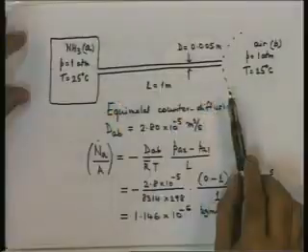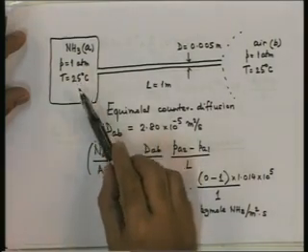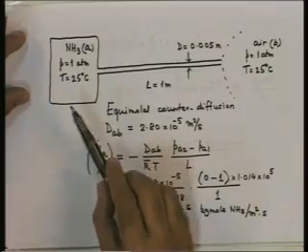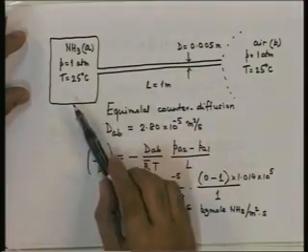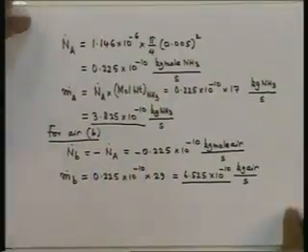and that takes care of our earlier assumption that during this process we have assumed a steady state, and we have assumed that the pressure in the ammonia tank, temperature in the ammonia tank and the concentration of ammonia in the ammonia tank does not change. We have demonstrated by means of these numbers that it is a good assumption, and even in 1 hour the concentration of ammonia or the molar density of ammonia in the ammonia tank would have changed perhaps by 1 part in 10^6, which is 1 in a million.